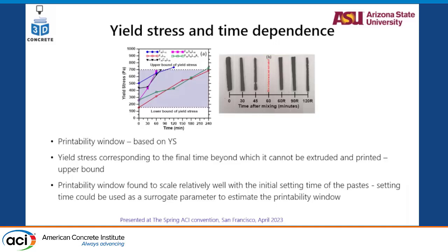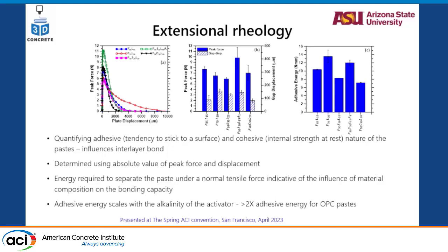So again, simulating the shear that you can have when the mix is placed in your mixer itself. So what happens with extrudability? Now, with layering, what happens with open time, what happens with layer interface, is a totally different question, which we will not get into now. I talked about extrusional rheology.